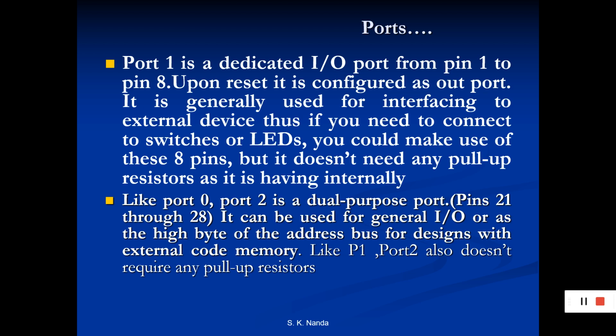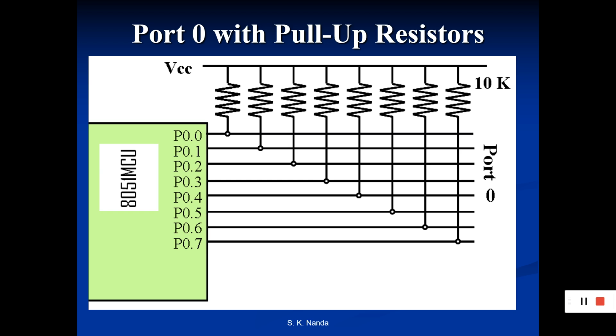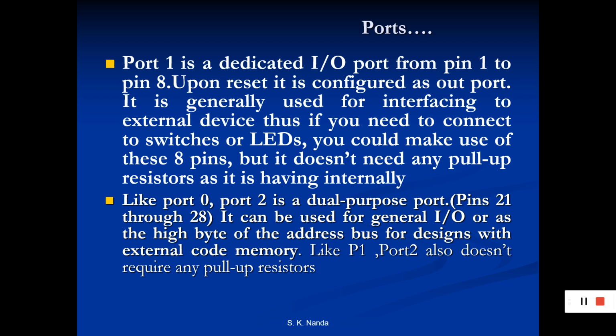Upon reset, it is configured as output port. It is generally used for interfacing to external device. Thus, if you need to connect to switches or LEDs, you could make use of these 8 pins, that is port 1. But it does not need any pull-up resistors as it is internally having those pull-up resistors built in it. जैसे पोर्ट 0 में हमको एक्सटर्नली लगाने पड़ रहे थे, in port 1 there is no such requirement.